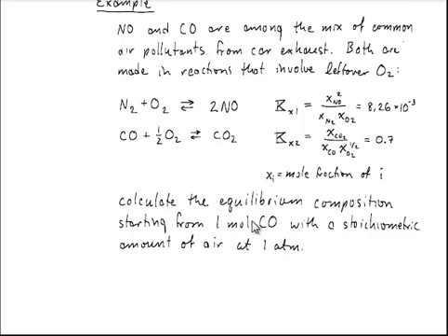That basically tells us that if I want to burn some amount of CO, I need some amount of oxygen, and that oxygen is going to come in with an amount of nitrogen. To model what really happens, instead of making all CO2 with nitrogen coming out of the reactor, we're going to end up with CO2 and some NO as well, because this reaction also proceeds just a little bit, at least, to the right.